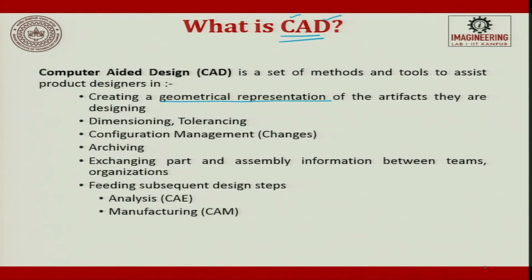Next, for the developed geometry, you are trying to give dimension and tolerance. What is dimension? 25 is the dimension. What is tolerance? 25 plus or minus 1. So, why is tolerance given? Tolerance is given because when we are trying to machine, there is always a possibility of variation from product to product or part to part. So, now what we do is we legalize and we also make sure that while assembly we do not have any problem. Wherever a part gets assembled, tolerancing becomes very important.